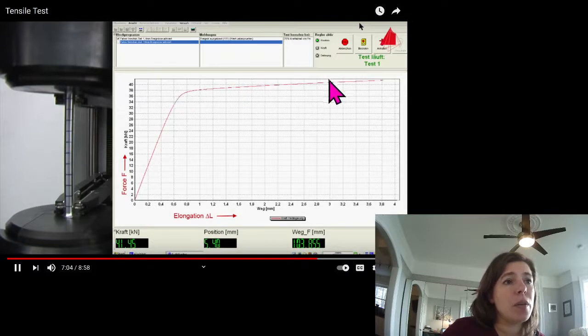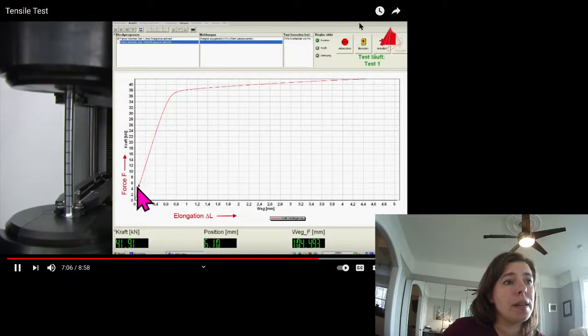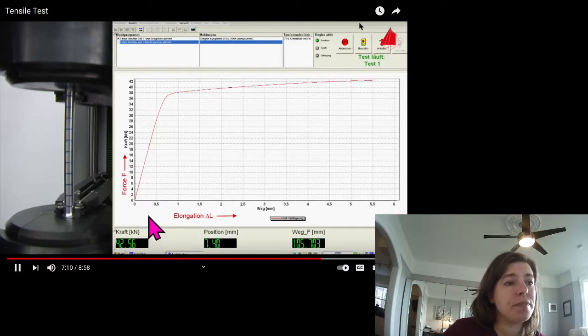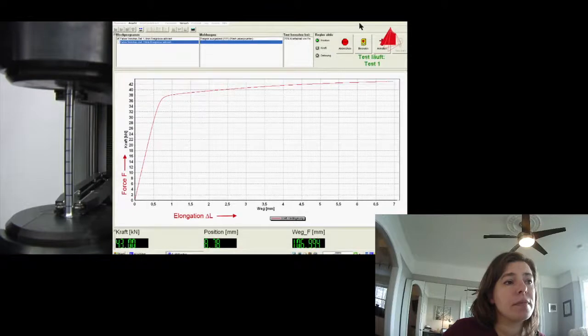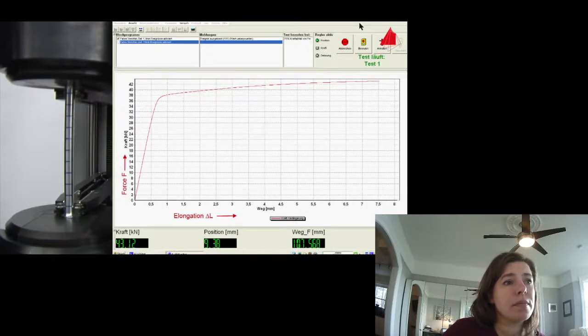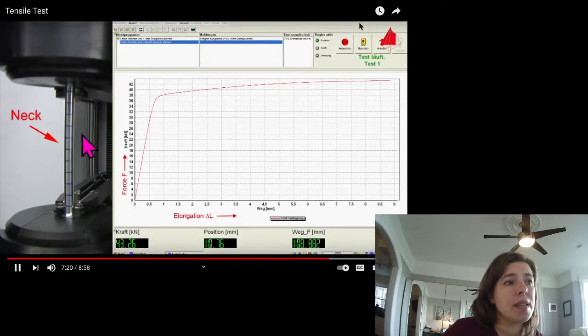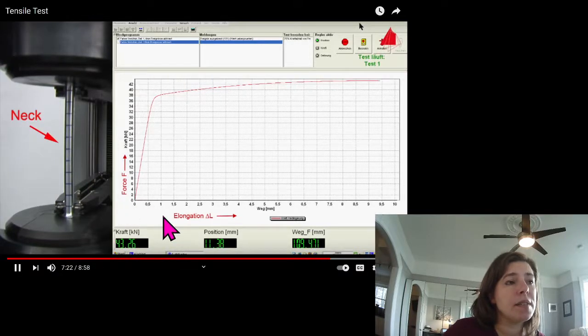Elastic zone, plastic zone. In the further course of the tensile test, the force increases, and the test piece again is strained uniformly along its length. At the point of maximum force, a neck develops, and all subsequent plastic deformation is confined to this neck until fracture finally occurs there.